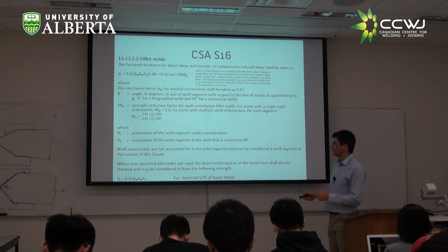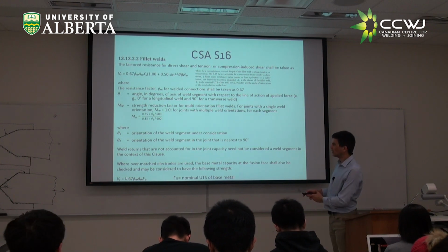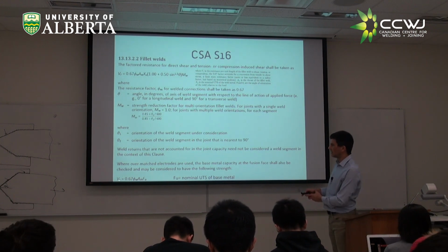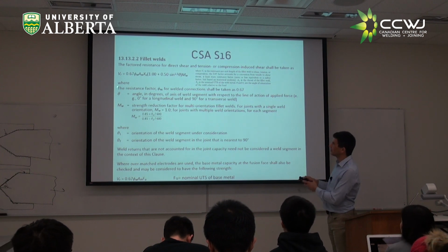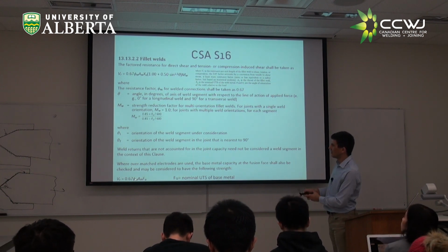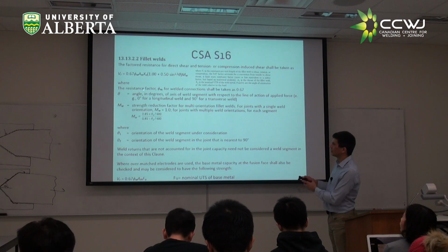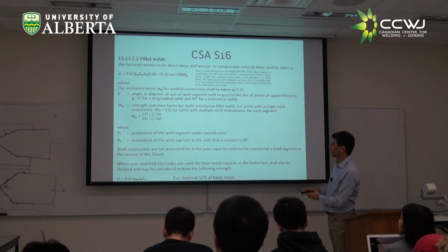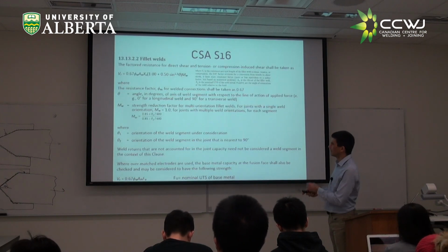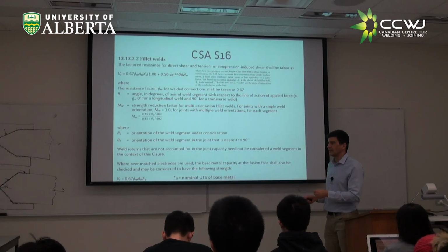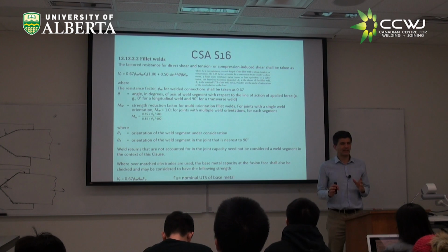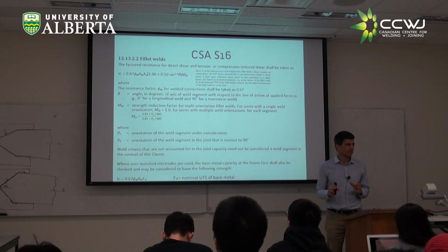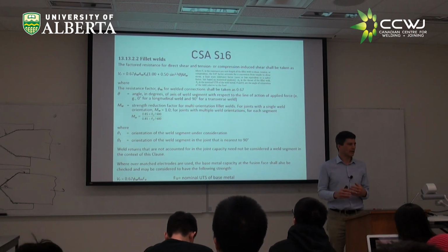That is this one here that says, my weld as a line has a strength given by this 0.67, just as before, my limit state, 0.67, same as before. Now it says AM, and I don't think I put it here, but AM is now the leg. It's the size of the leg, not the throat, because now we'll be breaking at the leg.